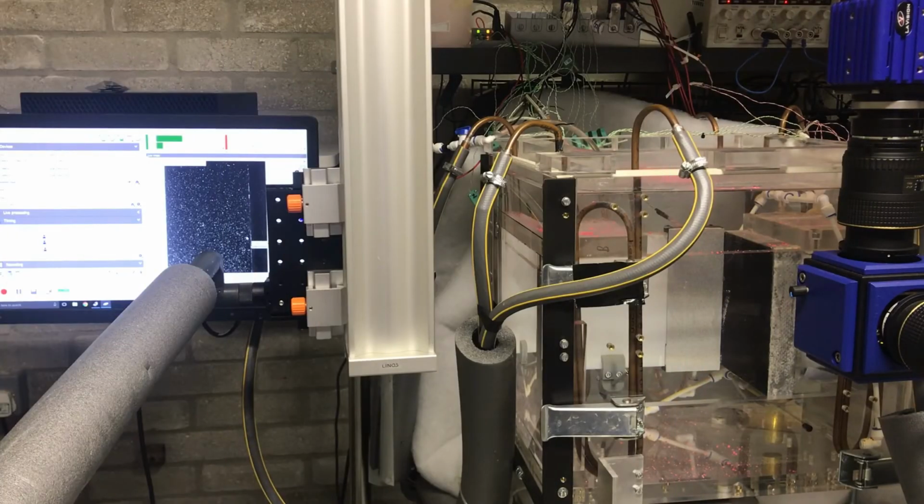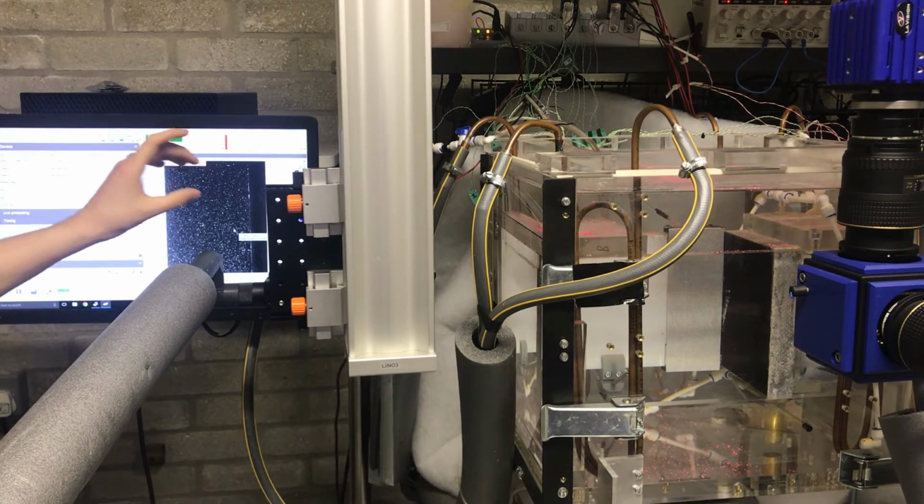So now let's assume that we were going to take some images, take some measurements properly. What we would do is firstly make sure we've appropriately seeded the geometry however we needed to, and we've given the system time to sort of homogenize and distribute the seeding particles. We don't want a clump of seeding particles here or there, we want them kind of distributed everywhere.